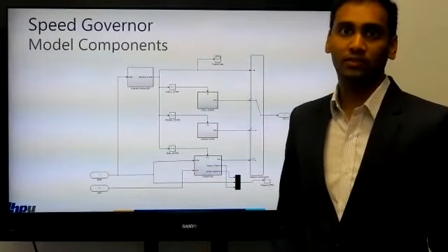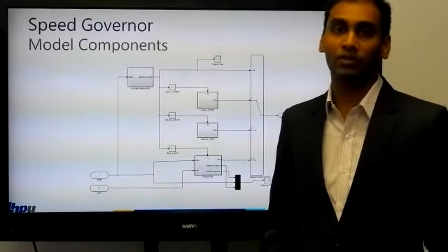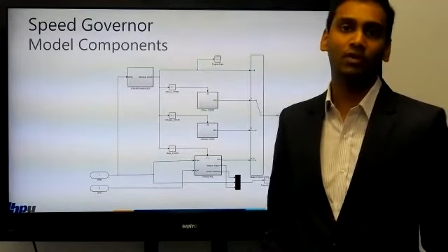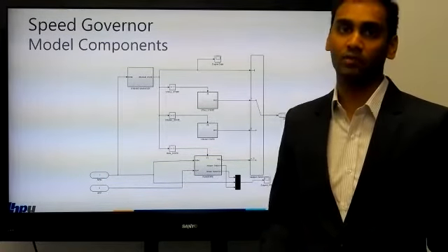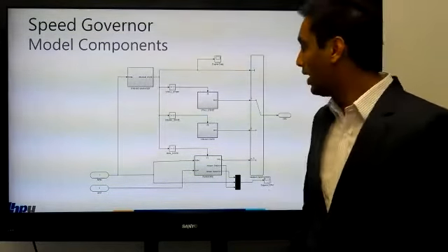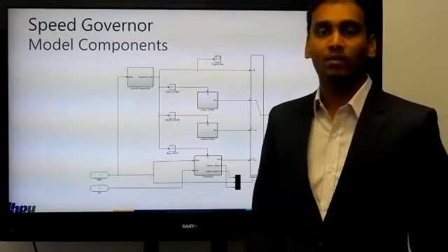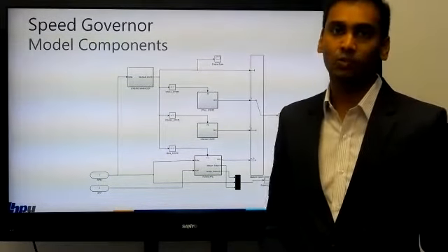So in these cases, for the stall state, you provide 0 fuel because your engine is switched off, and the crank state fuel depends upon the engine and application and how your engine responds to a certain input. And then the run state is the one where we place both our minimum and maximum governors once the engine starts running.